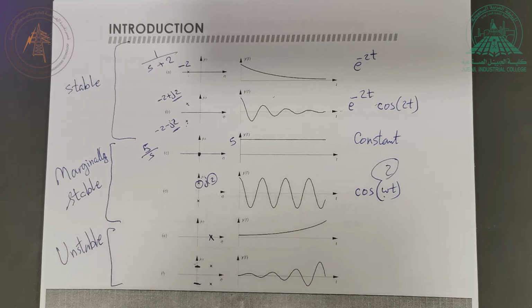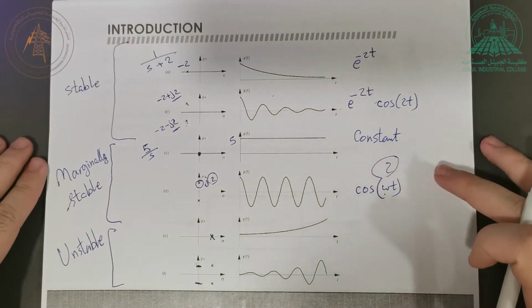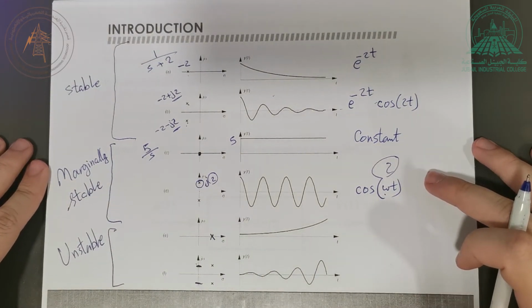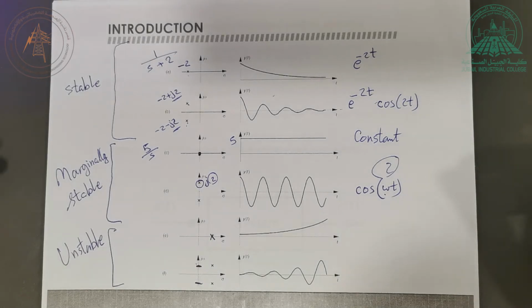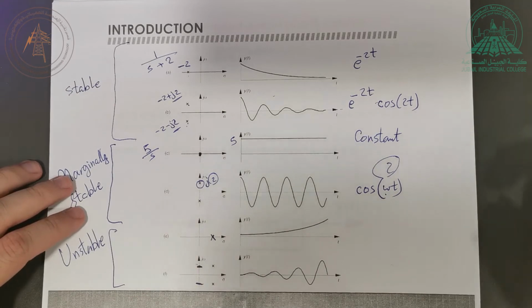If the op-amp becomes unstable, what happens? Instead of amplifying the voltage, which is the job of the op-amp, it will act like an oscillator. It will generate a signal even if you're not supplying a voltage. Regardless of what you're supplying at the input, it will create a signal at the output. But it's not out of nowhere, because it is using the energy coming from VCC, the biasing DC voltage supply.